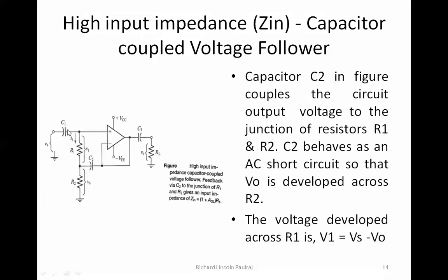Now see, this C1 I have designed. R1 we have put, R2 also we have put. C2 is here, C3 is here. But without my knowledge, there can be some additional capacitors or resistance here, which I have not designed and you have not designed. In terms of VLSI, these are called parasitic capacitors and parasitic resistance. Now let us take this junction between R1 and R2. I can have some capacitor here.